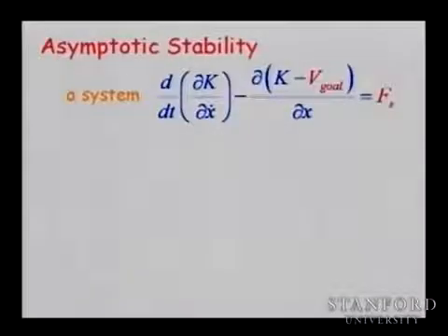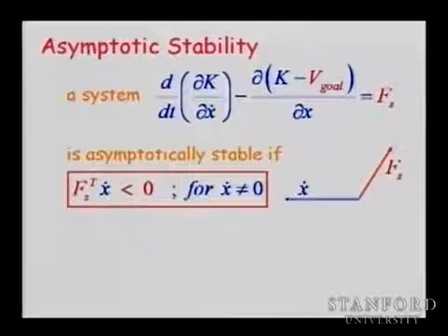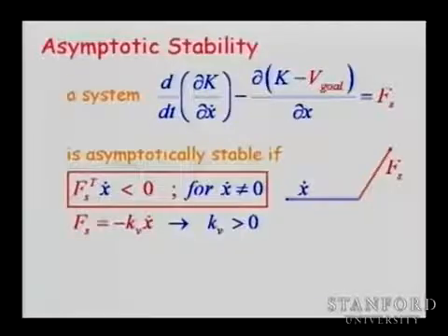So how do we stabilize it? Quickly. Damping. How do we select our damping? To oppose x dot, we put forces that satisfy this condition again. So it's very simple. You just select F to be minus kV x dot with kV positive.